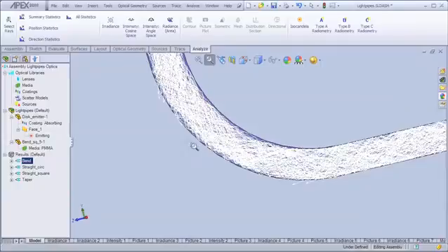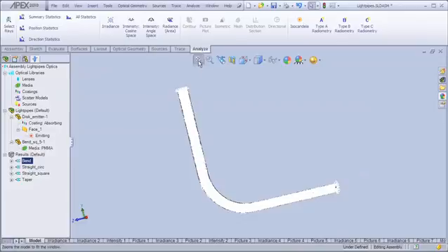Okay. In the area of the bend, you'll notice that we see some of the light exiting. Because of this bend, and 90 degree is a rather excessive bend, we see quite a few arrows leaving the pipe. This simply means light is leaking out. But you'll notice you see most of the arrows on this lower face of the pipe and few, if any, on this inner face of the pipe. What this allows you to do is to analyze where the losses occur to determine the right locations to put any mounting or other types of mechanical hardware.